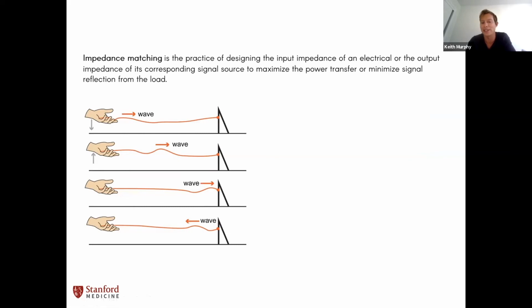So why do you think that's a problem, Kim? Yeah, you're just going to lose power input. Yeah, so your system is now less efficient than it could be. Mm-hmm. You have to use higher voltages and higher powers to get the output onto your system. So in that case, you would want to design a matching network. If you don't have a matching network and you're getting enough power, then maybe you don't need it, and maybe that's something you can forego.